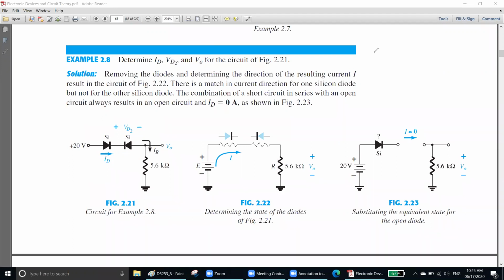Let me write. One is voltage difference. Another one is point voltage. What is the first one? Which one is voltage difference? Voltage difference means you have to find the voltage between 2 points. When your voltage has a plus and minus sign, you have to understand this is the voltage difference. In most cases, you find the voltage difference. Although I said find the voltage, or calculate the voltage, remember in 99% of cases you have to find the voltage difference. Voltage difference means your plus and your minus is given.